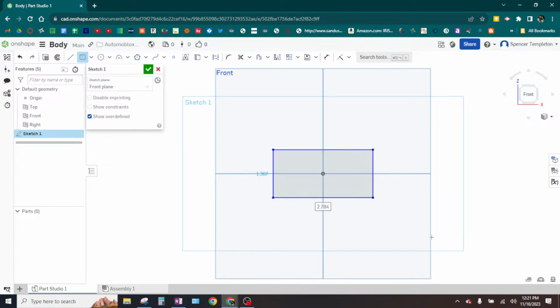Now, how tall is your rectangle? Well, take your calipers, close them all the way. I did center point, and I centered it on the origin. You're going to take your calipers, zero them, and then use the big teeth. You're going to go around and measure the height.